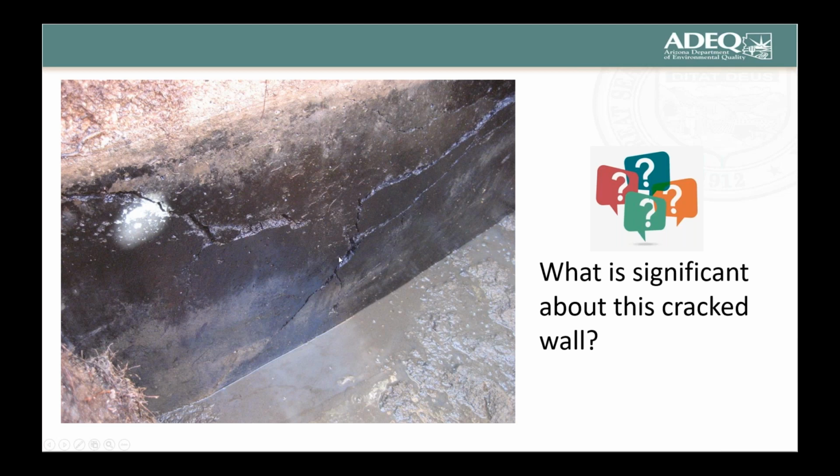Now, there is a soil that when you let water get to it, it expands, and you can have what's known as an expansive clay present. So if we have a tank that's cracked, started leaking water, and the water gets to the clay, it expands and opens this crack up pretty good. So that may be some of it.